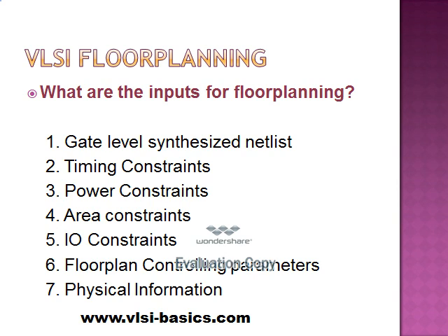The designer takes care of the design parameters such as power, area, timing, and performance during floor planning. These estimations are repeatedly reviewed based on the feedback of the implementation team, IP owners, and architects. The outcome of floor planning is proper arrangement of macros or blocks, power grid, pin placement, and partition blocks that can be implemented in parallel.